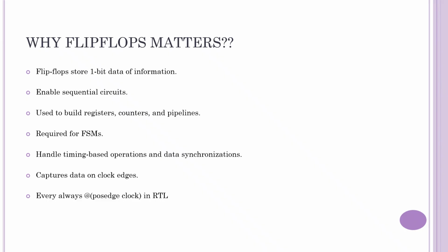Fourth, they are the heart of FSMs, finite state machines, which we use everywhere in RTL design. An FSM stores the current state using flip-flops. On every clock cycle, current state becomes the next state. Without flip-flops, no state retention, no FSM, no control logic.